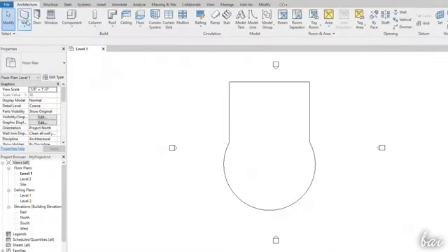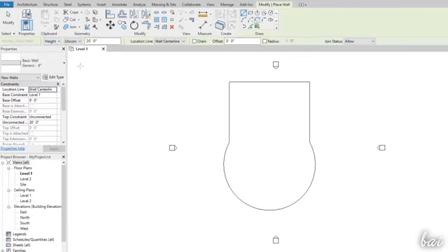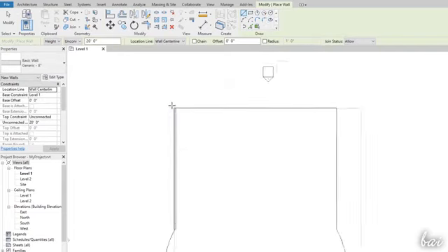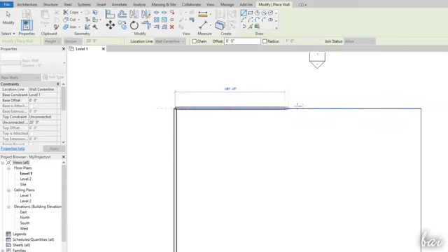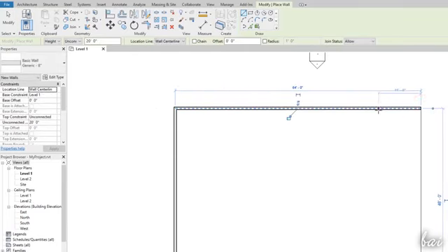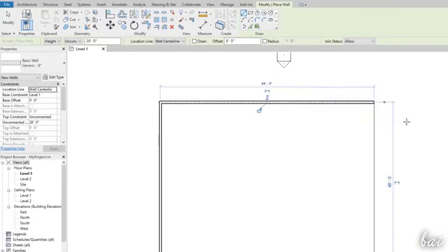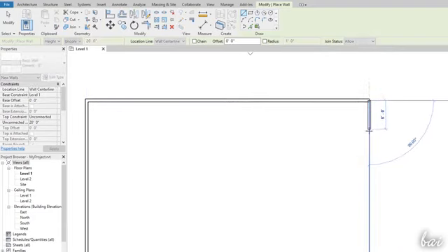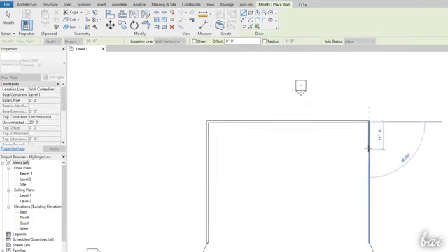After the floor, you can start dropping the walls with the Wall tool. Use the Drawing tool inside the Modify tab to follow the floor contours. The walls will merge automatically where they intersect on vertices. Also, use your mouse wheel to zoom in and be more precise.